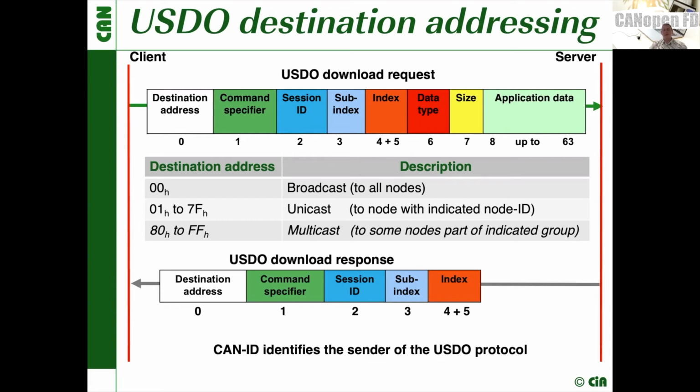Session ID allows differentiation between several transactions between the same or several devices. Subindex and index indicate which data element in the object dictionary of the server shall be accessed, either by read or write access. And another addition to classic CANopen, we have the ability to describe the data that is transferred via USDO, so in size and data type.